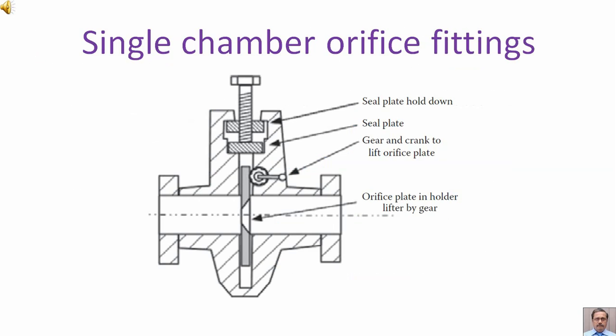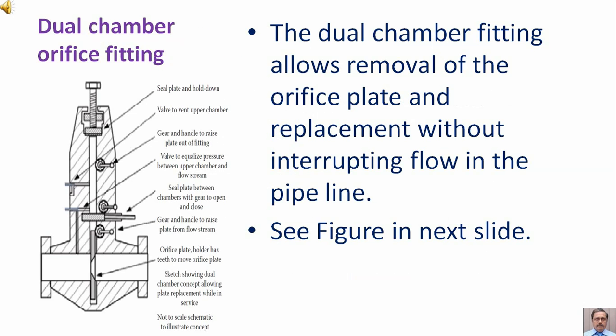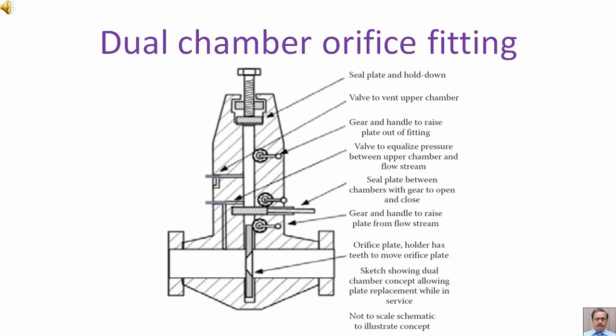Single chamber orifice fittings. Dual chamber orifice fitting. The dual chamber fitting allows removal of the orifice plate and replacement without interrupting flow in the pipeline. See figure in next slide. Dual chamber orifice fitting.